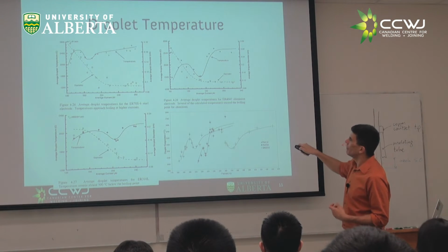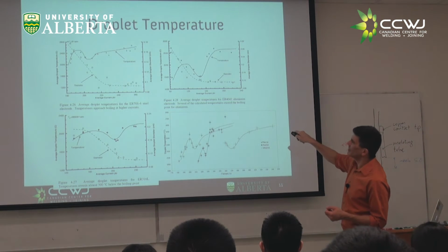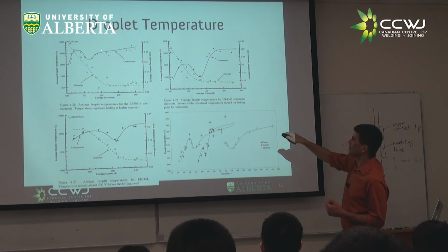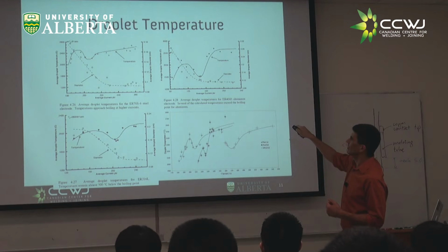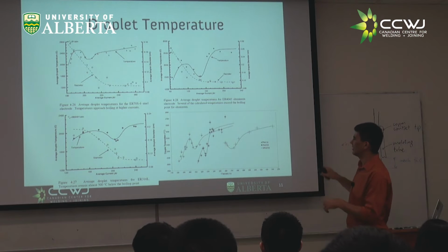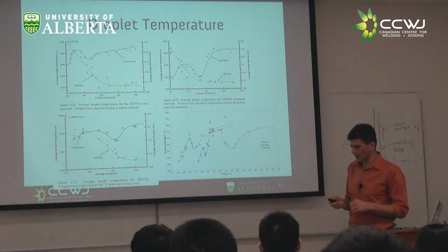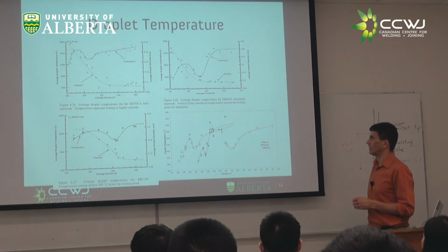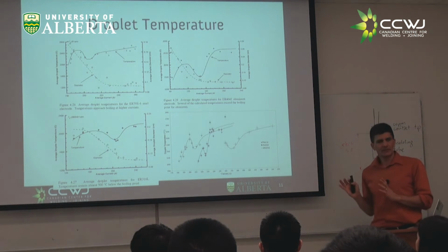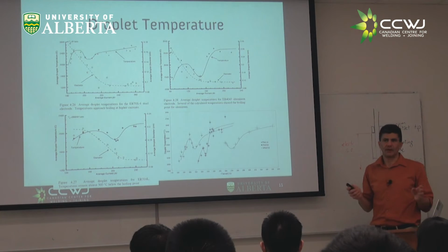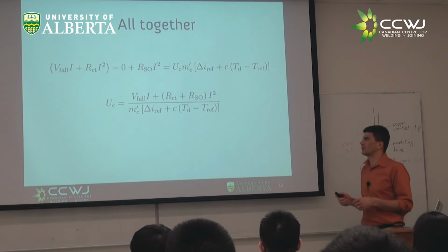So, but what matters is, look, when I said that the droplet is more or less 2500 degrees, yeah, it's what comes from this graph. In spray transfer, this is more or less 2500. Here you would have 2500. So it's, this is old. For aluminum, we're measuring lower temperatures now. Let's call them 2000, right? So this is how droplet temperature goes. And I'm going to call it 2500 C for the sake of most examples.